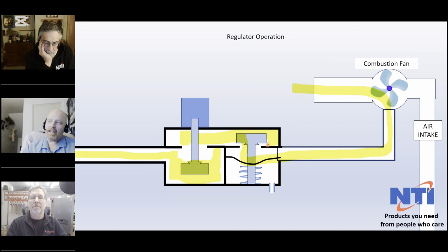They had previously had an old TI boiler there, and they never had any issues with getting much dirt in it. But obviously, the difference with the new boiler is it's a sealed cabinet versus a direct vent to the outdoors, which means that any holes you put in the cabinet for wiring, if the cover's not fitted correctly, if you don't put the screws back in, you get air leakage from the room.